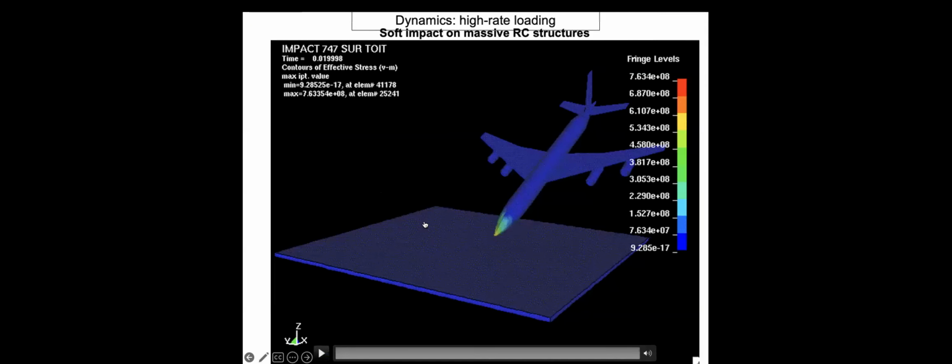The situation we had in mind was mostly that these are some kind of boxes where you store this material, and these boxes are done in a way that the roof is a simply supported slab. Since the boxes are next to each other, if you have an internal explosion, the roof can lift off, and the next box has the effect of the explosion reduced, because it goes to the roof and not to the adjacent boxes. The second point is that the real model, with an airplane entering at 90 degrees, which is the worst case scenario, is definitely not easy to reproduce for a structure which is the same size as the airplane.